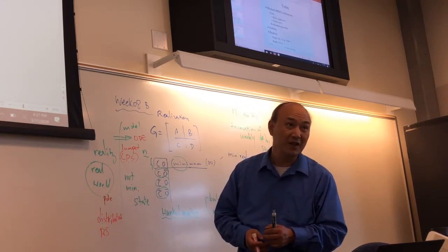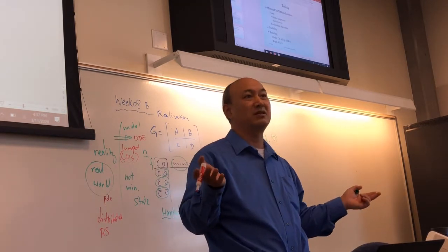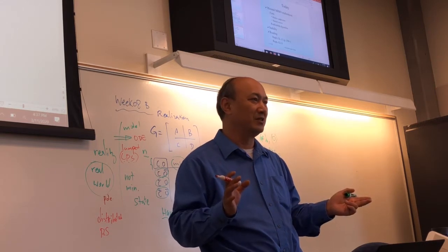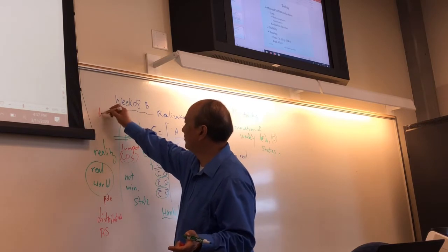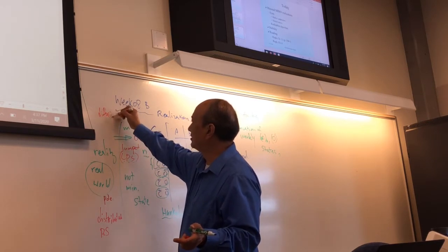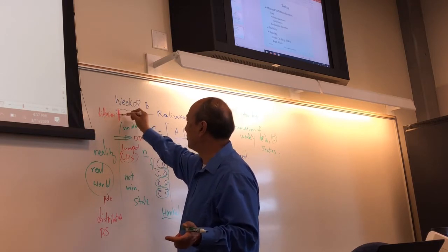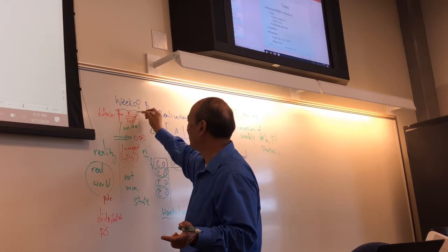Say for example, the temperature of the room. Okay, it actually follows a diffusion equation. But in the real world, it's a diffusion equation. This is already an infinite dimensional system, but then we use approximation, k over Ts plus 1 times e to the minus Ls.